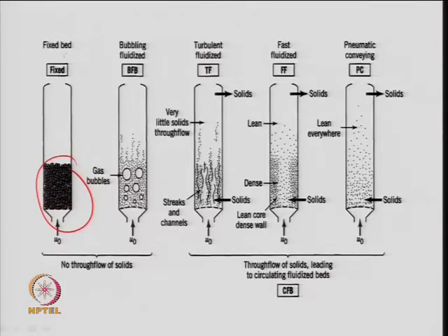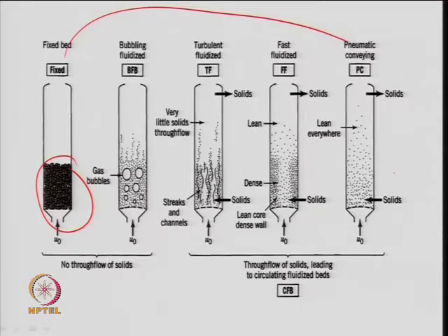So, depending upon the superficial gas velocity, you can have a region from a fixed bed to a kind of system where the particles leave the bed. This fundamental thing can be used in spray tower units where fine powder is moved from the bottom to the top, and it can also be used for conveying. Powdered material can be transported through the unit. The solid is fine and you have very high velocity, so it is a kind of pneumatic conveying system, where the solids leave the bed continuously along with the gas. It can be a kind of illustration also.